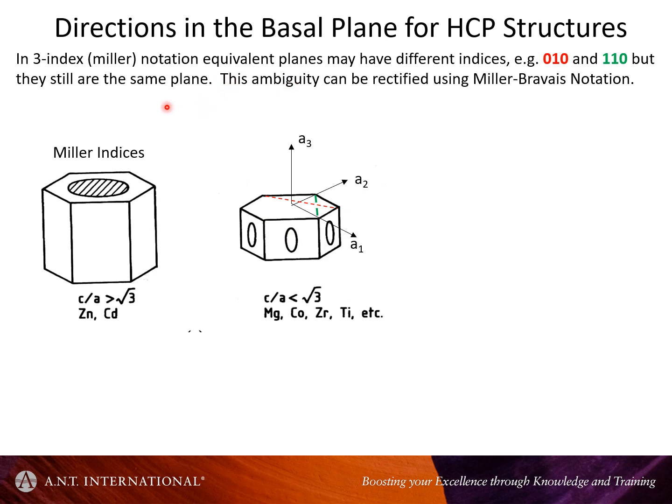And how do we define the crystal structure? You do this with respect to an axis system. In this case, for example, the common one would be a Miller indexing system. So that would then help you define what plane or what direction we're looking at. And for hexagonals, this would be a typical Miller indices. So we'd have a1, a2, and a3, which is the c-axis in this case.